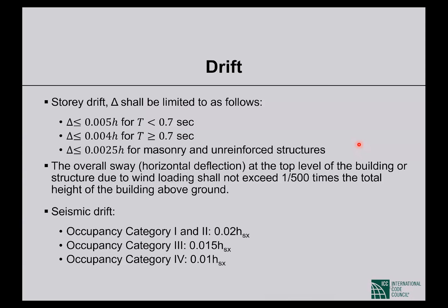Now you can argue that, well, if I pull a structure with different amounts of force, the time that will be required to come back to the original position or to make one cycle will maybe be different. That is not the case. It depends on the mass and stiffness of the structure, and the same structure, whatever the amount of force you pull it, will take the same amount of time to make one cycle.